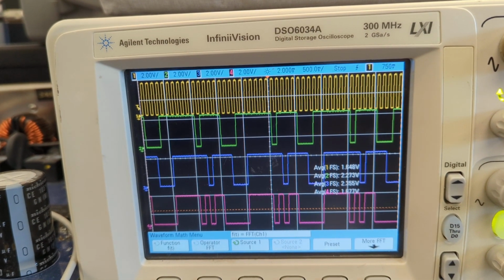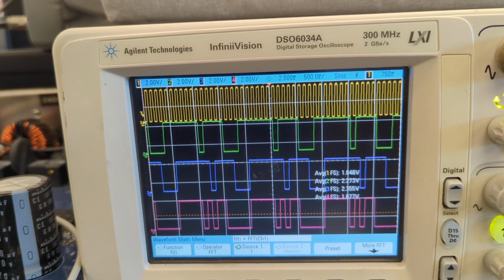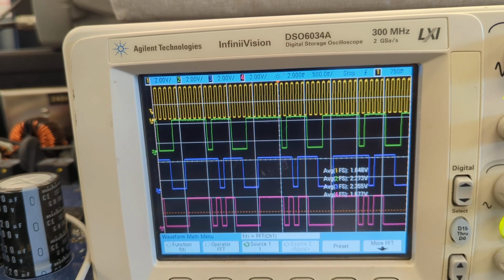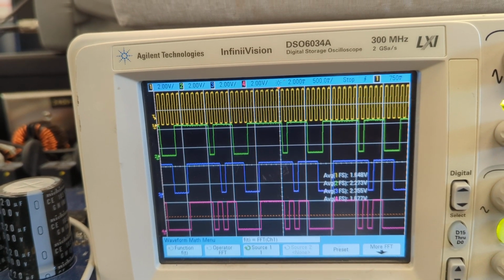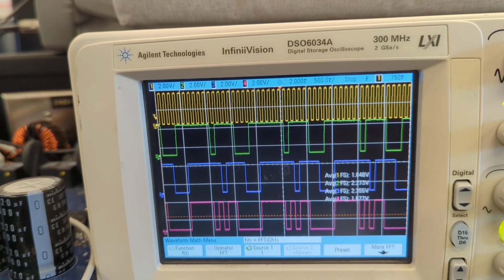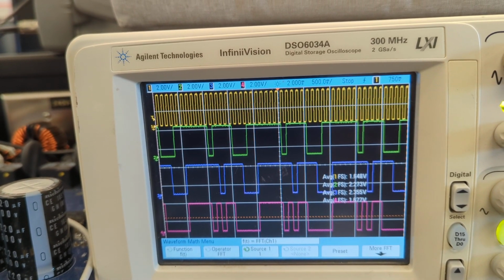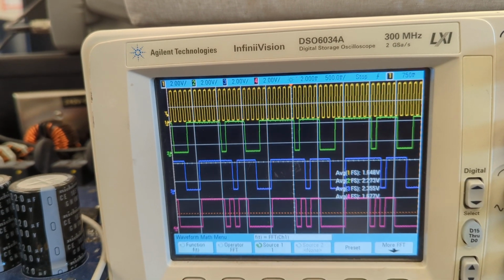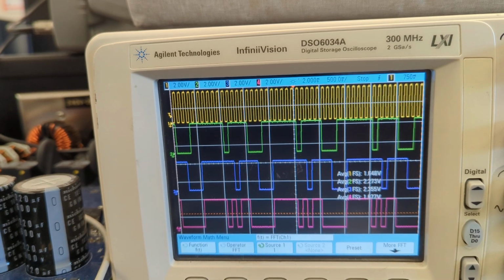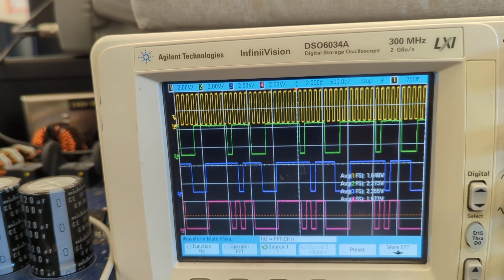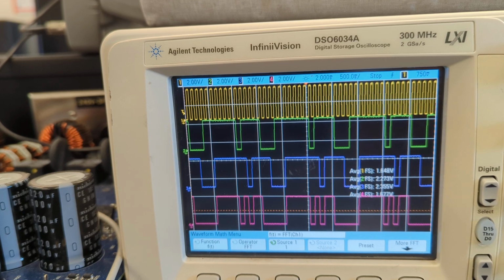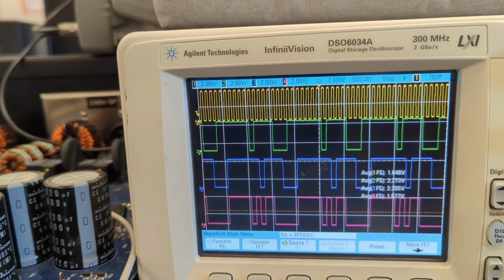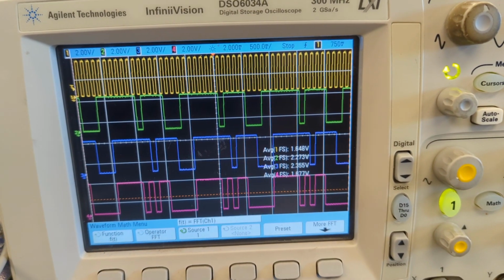And if I have another signal that is also a 1 out of a 2-bit signal, which means 4 time slots, so one 1 anywhere in 4 clock cycles would be another 1/4. So the AND gate will multiply them together just by taking the AND of the function, and on average you'll get 1/4 times 1/4 is 1/16. So every 16 clock cycles, somewhere in that bit stream, you should only see one 1.